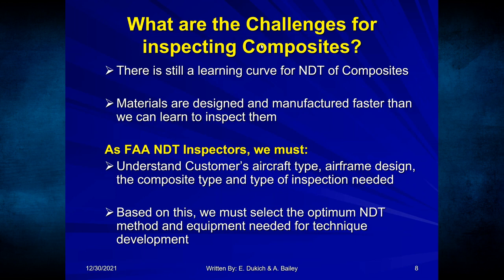So what are the challenges in inspecting composites? Well, we in NDT still have a learning curve for NDT of composites. We have to ask manufacturers, what materials are used to design or manufacture this aircraft? Because they're designing them and manufacturing them faster than we can learn techniques to inspect them, because some of the older techniques are not sufficient for testing these new materials.